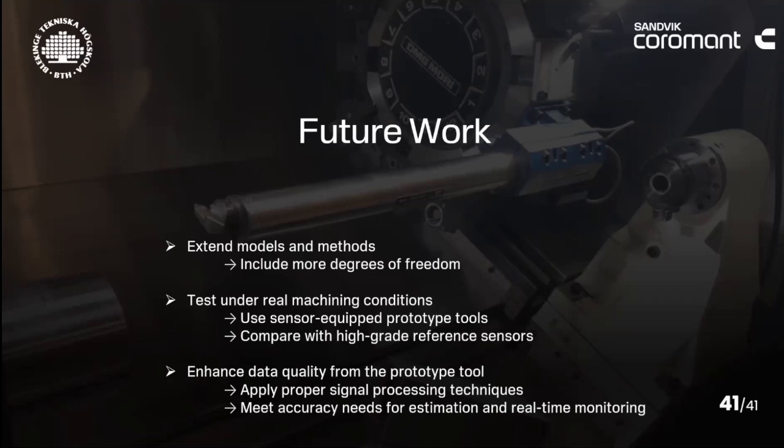And finally, since the embedded system often produces low-quality data, proper signal processing techniques are crucial to help us accurately estimate the input force and tool-tip deflection, and also for real-time monitoring during machining.